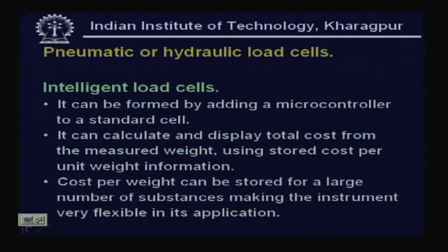We basically discussed two basic load cells, the link type and the cantilever beam type. As I told you earlier, sometimes people call the link type load cell the column type load cell, and the other is the cantilever beam type load cell. You will usually find that the cantilever beam type is used for slightly lesser loads, whereas the column type load cells are usually used for larger loads. This ends lesson 5 of industrial instrumentation.